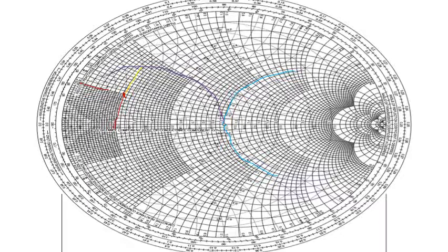Normally we do not highlight the dotted circle. It is just for your reference I am doing it. This is a dotted circle. So we are supposed to move the point either to the dotted circle or to the solid circle. Since we are on the dotted circle side, we will be on the left hand side. So as shown by the yellow color, we are supposed to move the point ZL to the dotted circle point. The arrow I am drawing is in this way, meaning you have gone from this ZL point, touched this point, and you are at the dotted arc point.